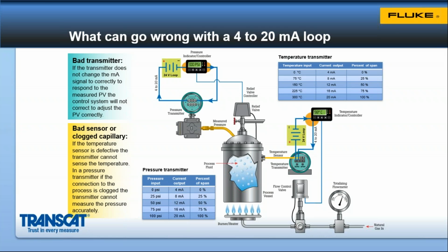Well, it may not be the pressure transmitter that's bad. It could be, but in general, he's inferring that something's wrong with this particular control loop. It could be the transmitter, it could be the I/O card, the power supply, or terminations in wiring connections. Another element that can go bad are the sensors that go into the transmitters.